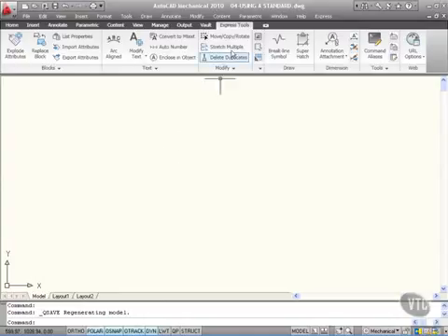Now you'll see at the moment I've got 04 using a standard DWG open. What we're going to do is utilize the settings in this particular drawing, and then set ourselves a standard. Now standards are already preset in AutoCAD Mechanical, and we'll look at those in a moment. The first thing we need to do is set our units. Now we've done that before.